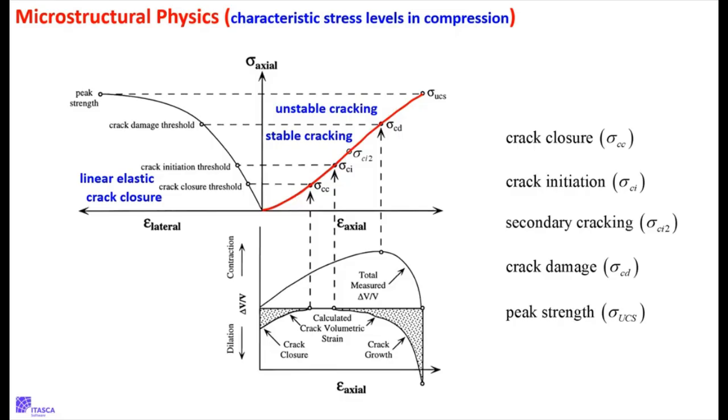Yes. Okay, cool. Now, here's a really interesting thing. Take this Lac du Bonnet specimen. This is the curve you get. Boom. First of all, you can take 25 of these specimens from exactly the same place, right next to each other, maybe one giant core. If you test all 25 in exactly the same conditions, you'll get 25 slightly different curves, but they'll be quite similar.